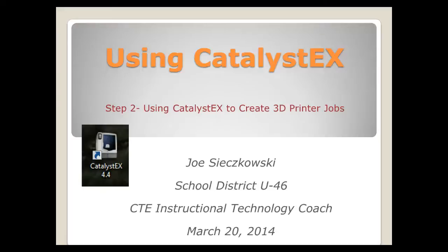Welcome to step 2 for creating a print job for your 3D printer. This step, after exporting from Autodesk Inventor, is going to be how to use CatalystEX to develop the type of file needed to send to your 3D printer.